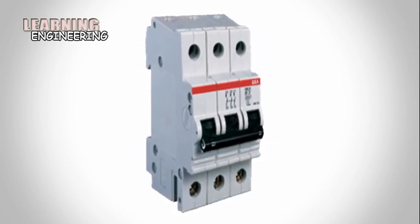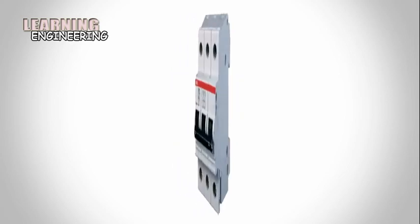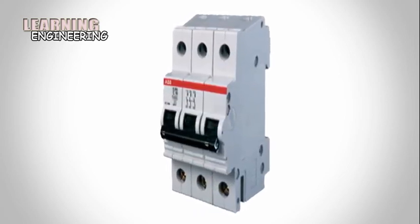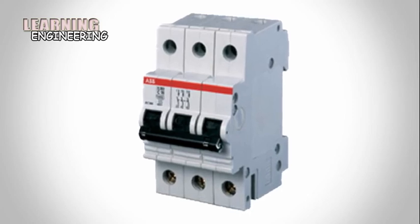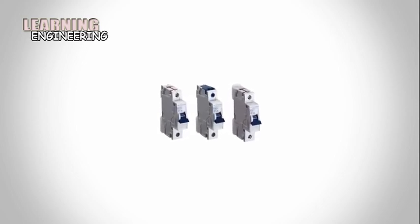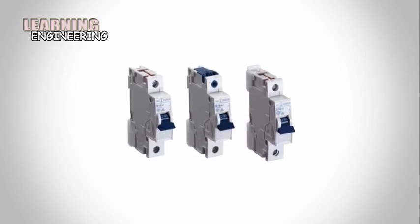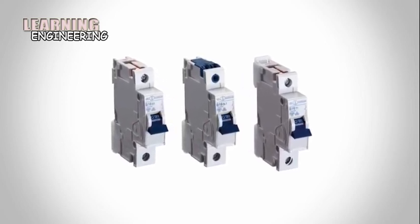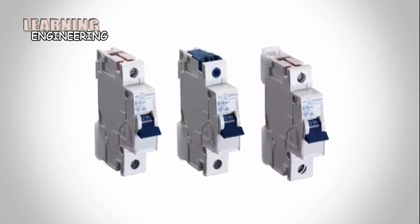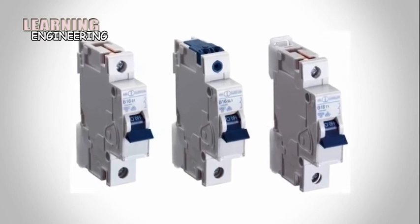It is usually permanently installed in equipment. It generally has two mechanisms for breaking the current, a magnetic portion which opens with a large current and a thermal part that also opens under overcurrent. The thermal part has a lag, so these typically go slower than a fuse, but with very high currents the magnetic part will open quickly. The circuit breaker usually has a button or handle to reset it after it has cooled down. Circuit breakers are usually more costly and larger than fuses.